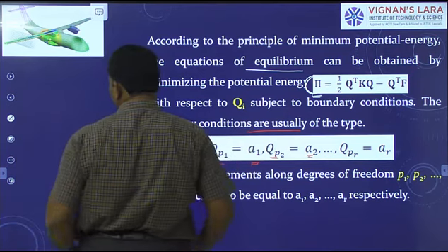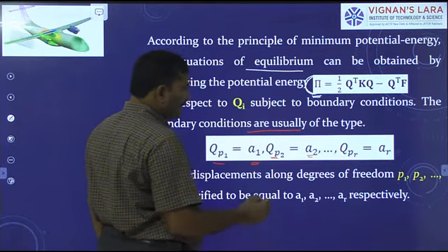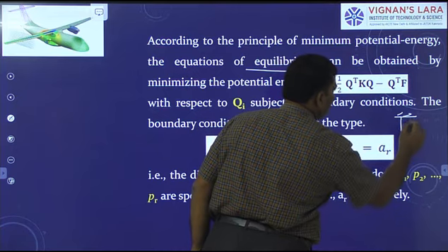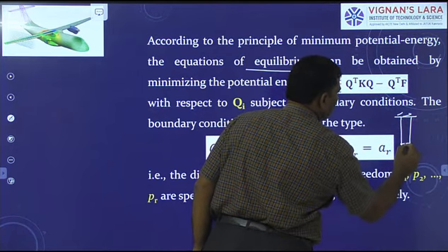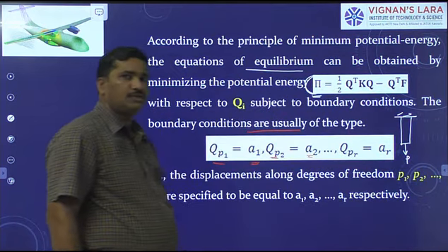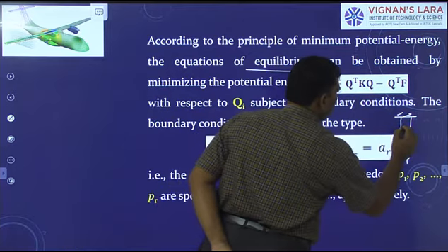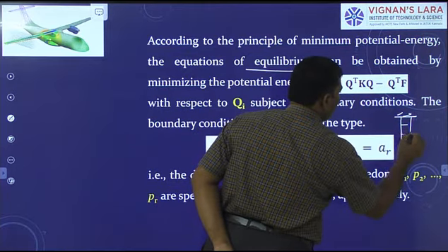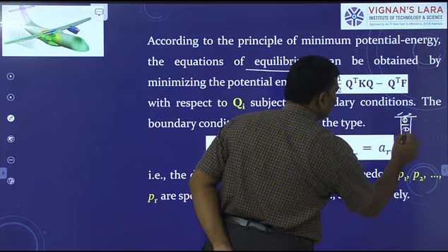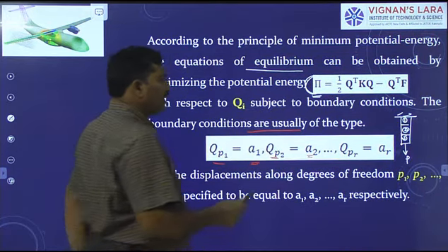I take an example and explain, right? Now, I take an elastic solid like this with uniform cross section. This is subjected to a concentrated force P. When we implement the finite element method, according to the basic idea, I divide this into three finite elements: first element, second element, and third element. Now, where are the nodes?